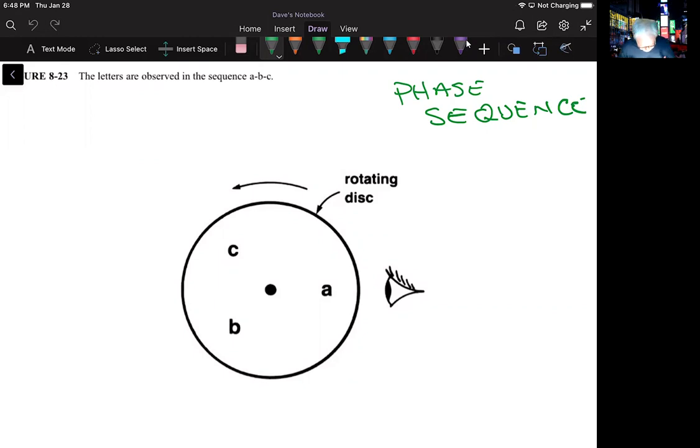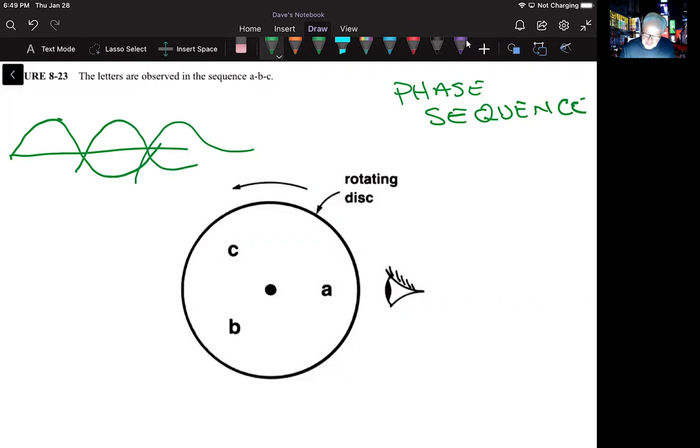Okay, so consequently, in three-phase systems, phase sequence is as important as the frequency and the voltage are, because we have to know which way the motor is going to turn, right? That's important. A load is designed to, and a system is designed to turn in a certain direction. The phase sequence means the order in which the three-line voltages become successively positive, right? When we're talking in terms of our sine waves, and there are three of them, as they rotate through, which one, what is the phase sequence?